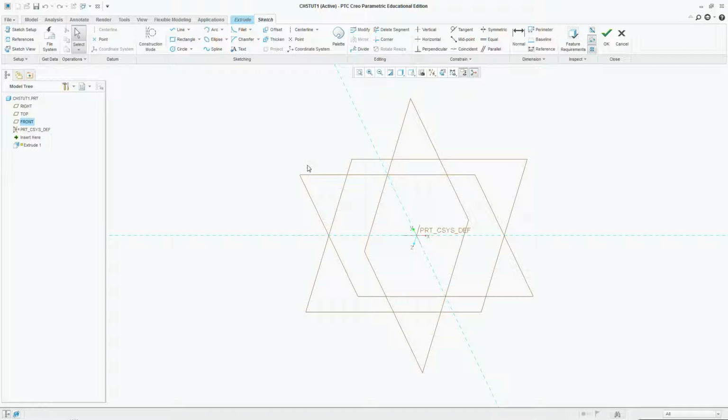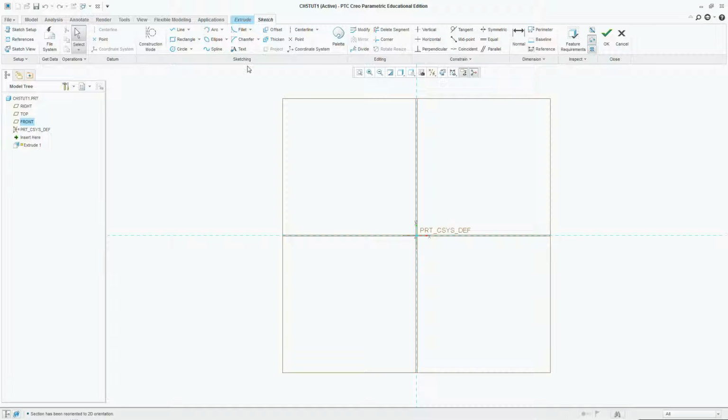And then it has a couple of other steps, but we can skip those because it just selects the plane that we need. Now I can click right here to go to sketch view, which might make it a little bit easier to sketch this object out. So that's what I'm going to do, and I am going to start with a circle. So we'll draw the circle, which has a radius of 8, so it'll have a diameter of 16.